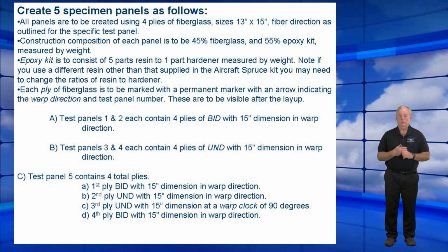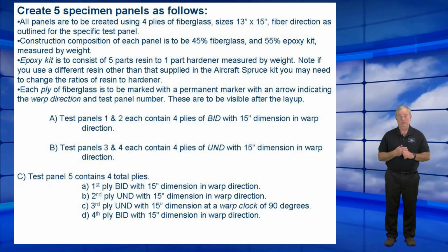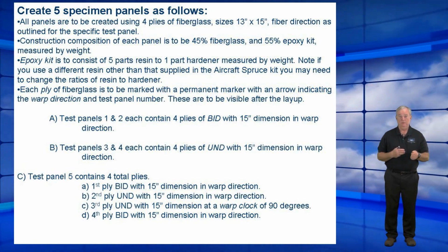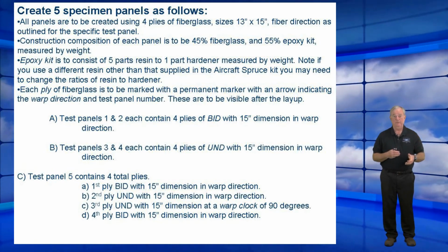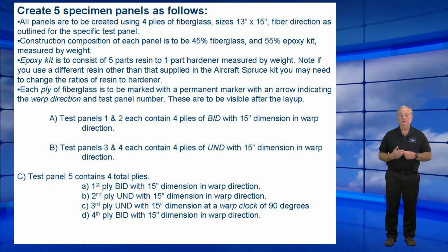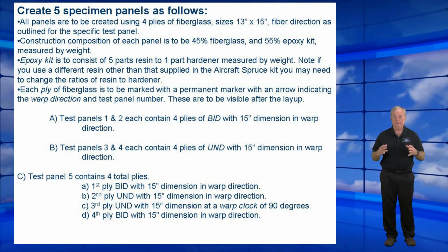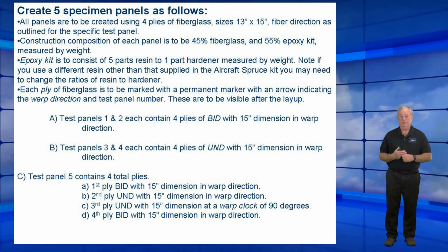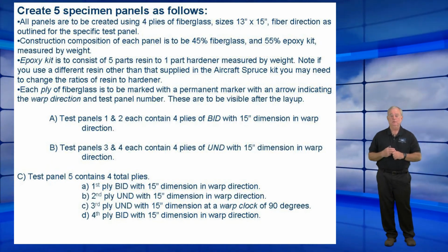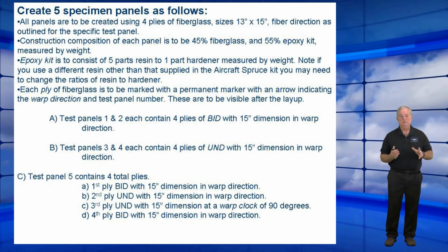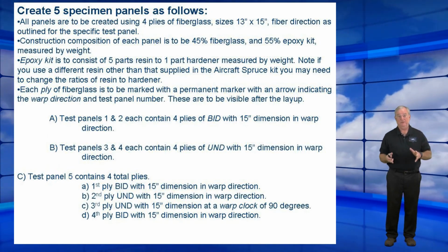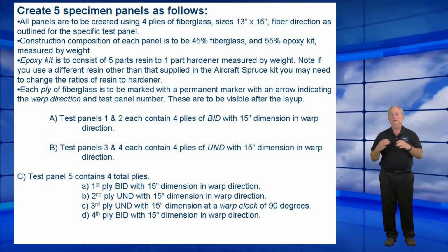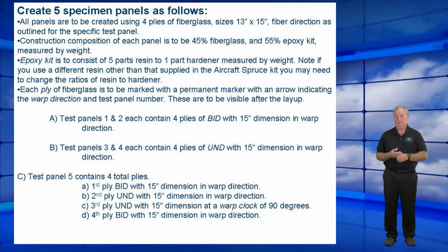So we use bending specimens where we clamp them to a table using a pair of vice grips and then load them using a plastic jug filled with varying amounts of water so we can vary the weight on it. So it's a very simple testing procedure, not very expensive testing procedure that can be done in a classroom. You don't have to have a laboratory environment.